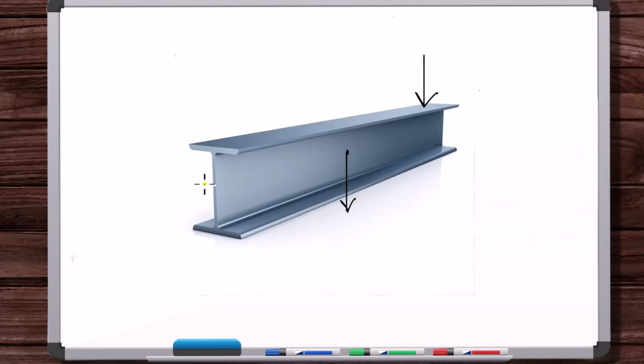Okay, so with that in mind, we know that there are potential resultants. So the resultant under the load distribution, there's a resultant force preventing this from translating and rotating. Now, we could put a force in the Z direction, a couple moment preventing it from rotating about this axis. But if we look at our loads here, this is a planar problem.